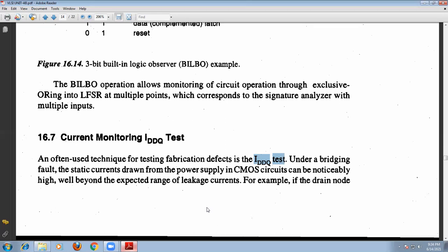This requires more testing time, but fault detection capability is greatly improved with small currents, by monitoring the IDDQ in various parts of the device under test.